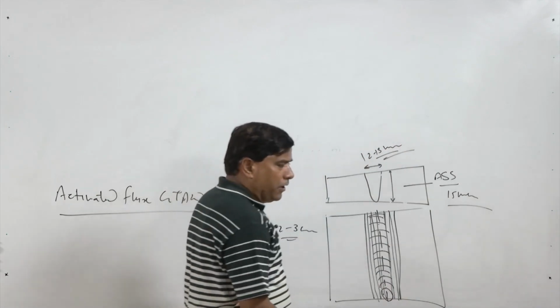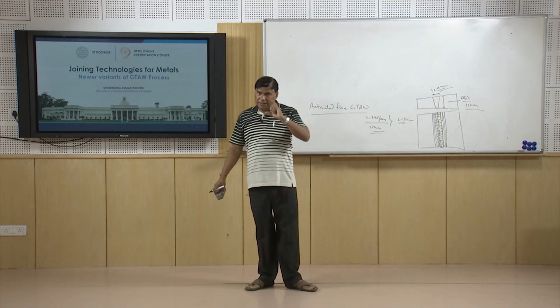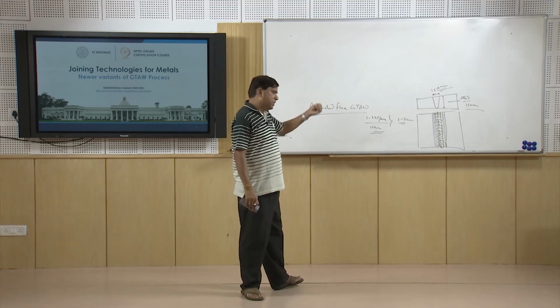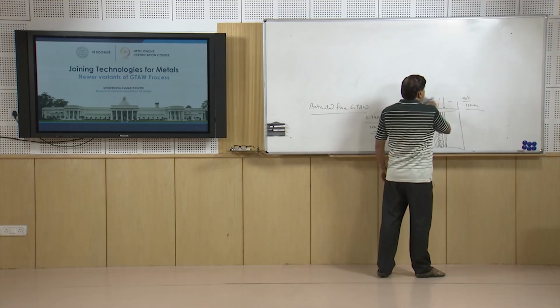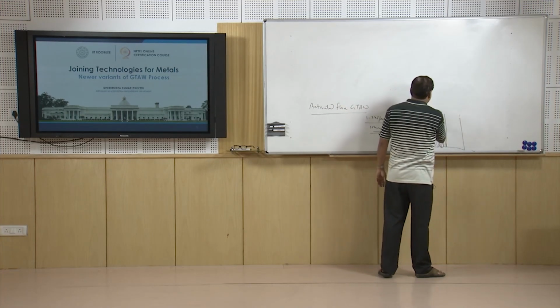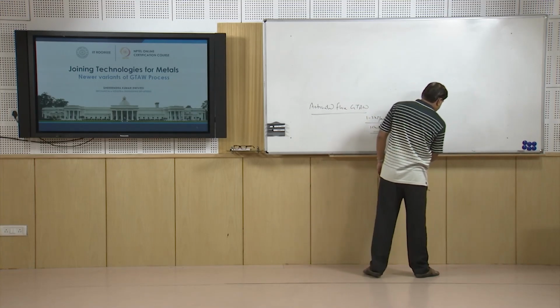A width to depth ratio of about 0.9 to 1 has also been achieved, and this helps in reducing the angular distortion and increasing the depth of penetration